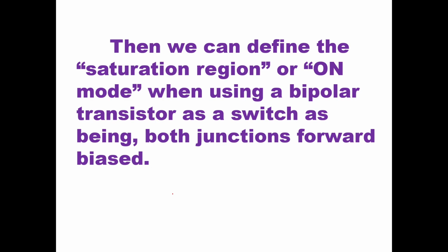Okay, so this is how a transistor can work in the cutoff region and saturation region. In the cutoff region, the transistor will be in the off position, that is an open switch, and in the saturation region, the transistor will be in the closed position, that is an on switch. So on off operation is possible by properly biasing the transistor. Okay, so this is how the transistor works as a switch.